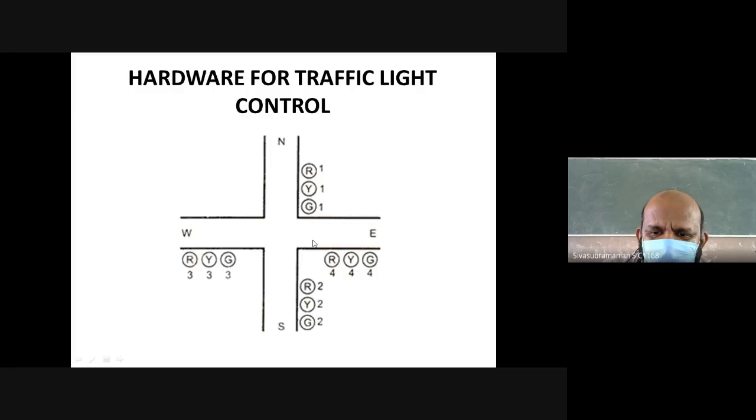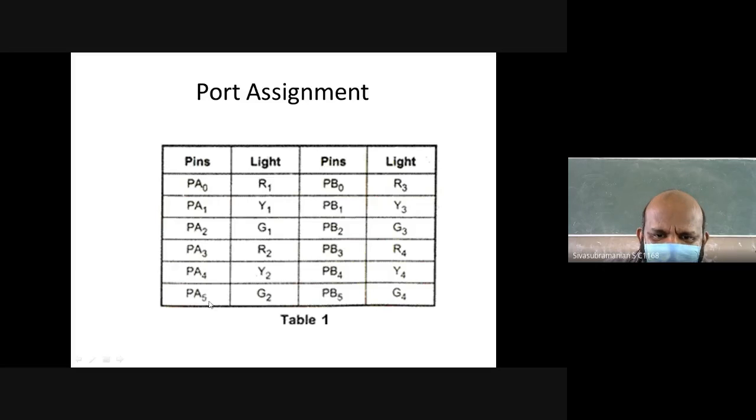R1, Y1, G1, R2, Y2, G2. I am using my port A. Out of the 8 pins available in my port A, PA0 to PA7, I am using PA0 to PA5. 6 pins I am using, right?